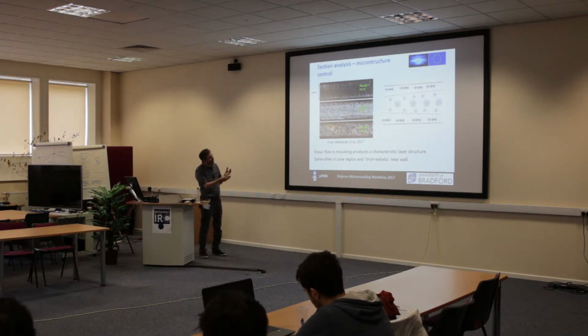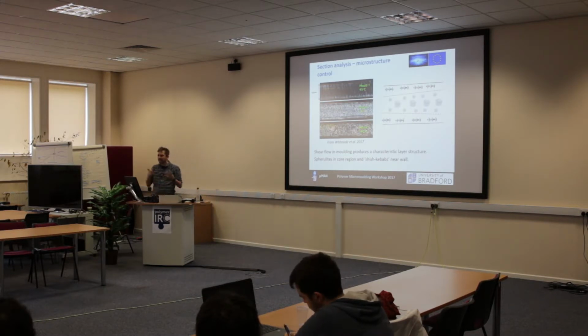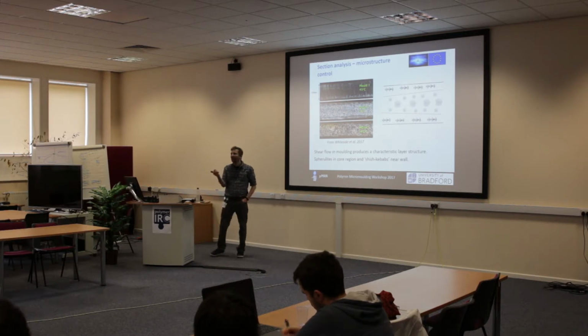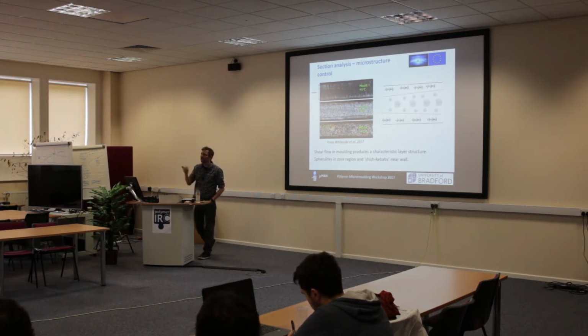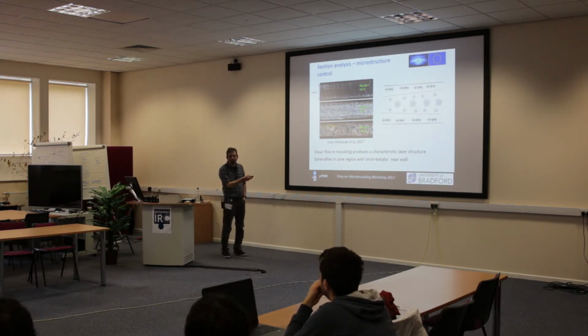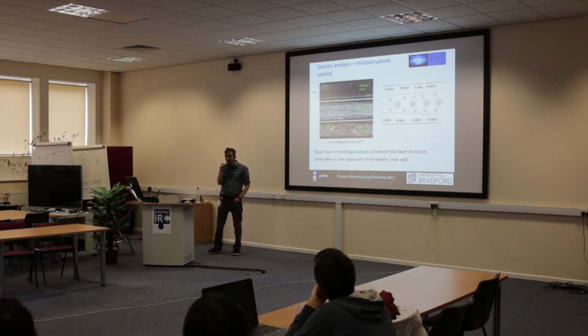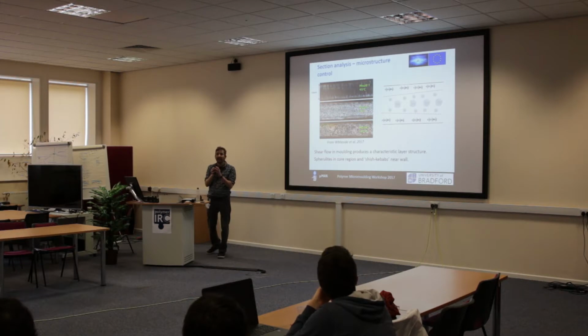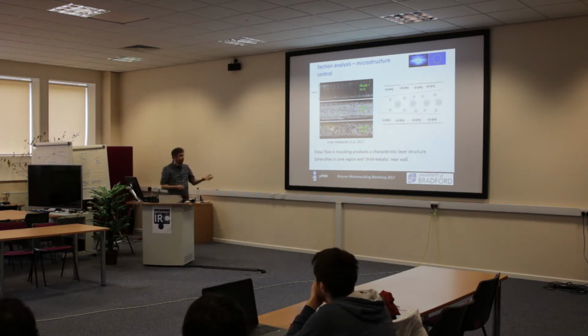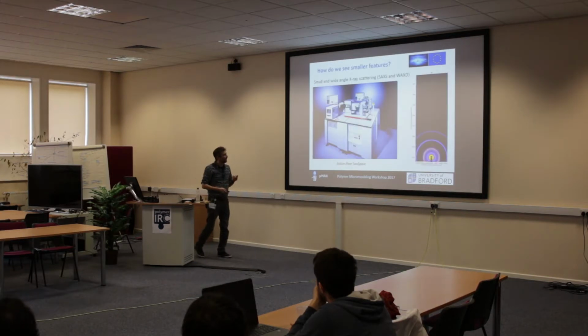And so you always end up with this characteristic multi-layered part, okay, which is very, very complex. Now, if you want a part that wears very well, okay, that's one of the key things it needs to do, to be able to be under a wear situation for years, then you want a high level of crystallinity at the wall, and you want a high level of very strong crystallinity at the wall. Your crystals need to be the right crystals to withstand being gouged the whole time, okay? So we begin to try and understand exactly what's going on in here.